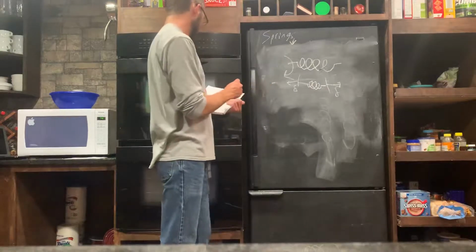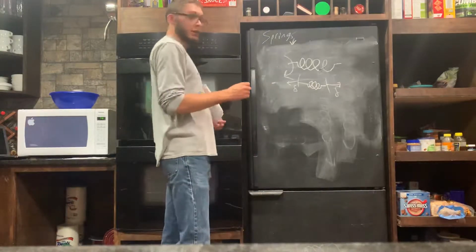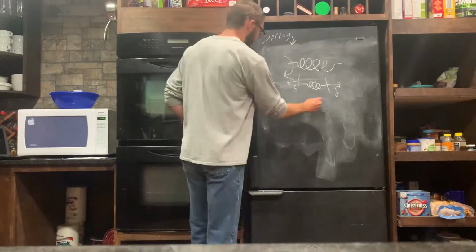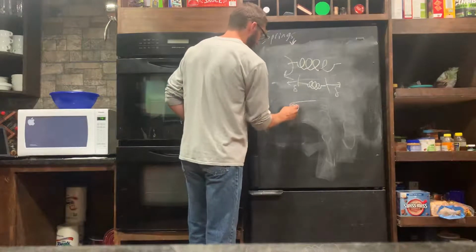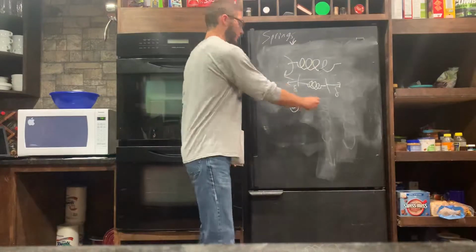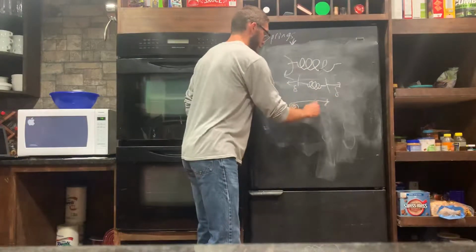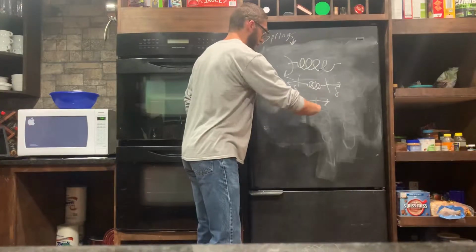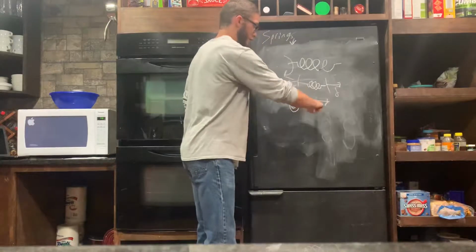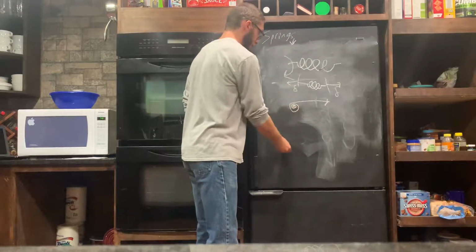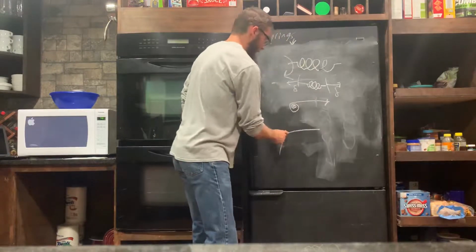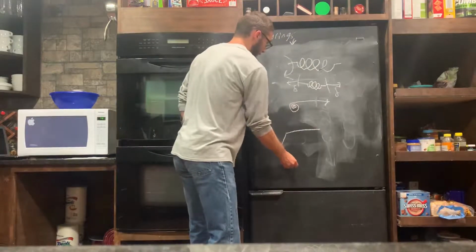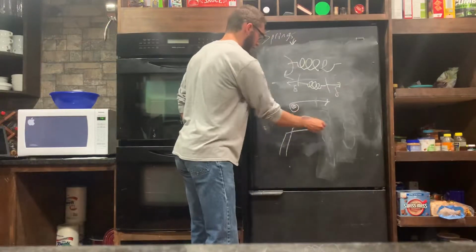The fourth one is a constant spring, which is a little stranger because its coil is all in one spot, and as a force is applied, let's say out this way, this is going to keep extending and this is going to unravel. If we had a graph of this and we showed the load, it's actually going to stay constant after it hits this point, versus going something like that.